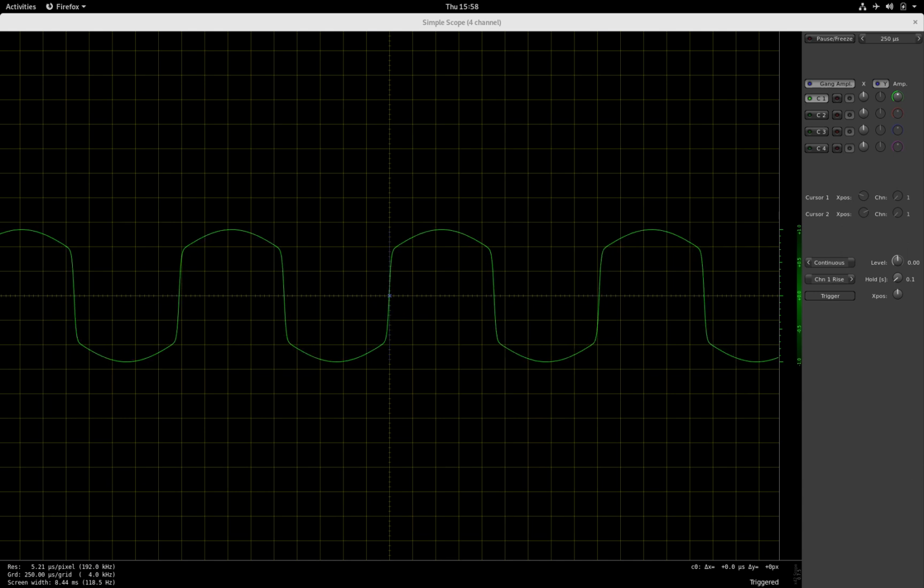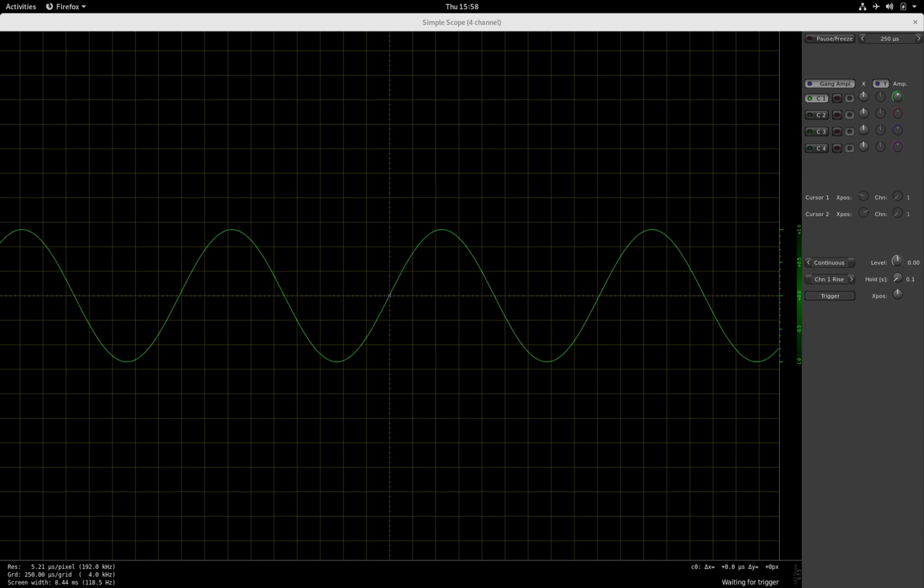So this is what the drive control does to the signal. Now I will put the overdrive effect in bypass mode again, so we will have a sine wave again, and instead of an overdrive effect, I will kick in a distortion effect. And we now basically see that nothing happened to the signal, which is because the distortion effect is currently set to a gain of 0 decibels.